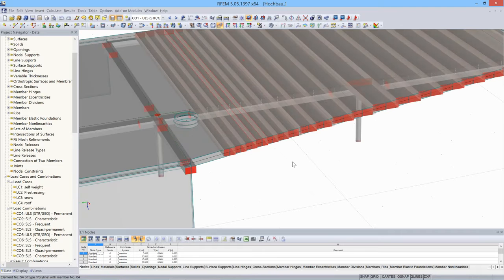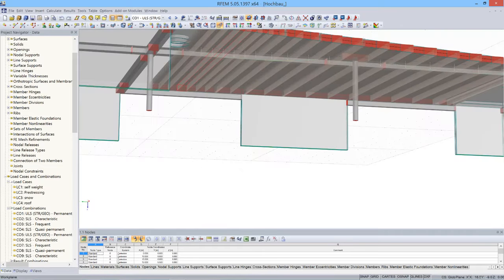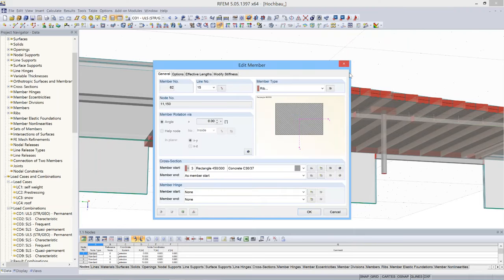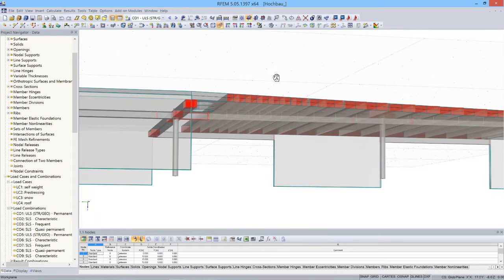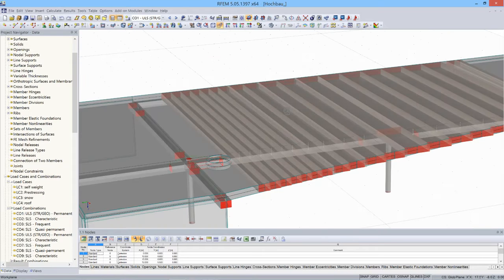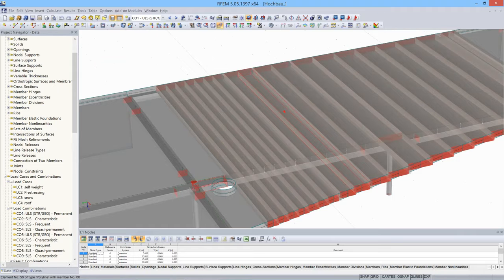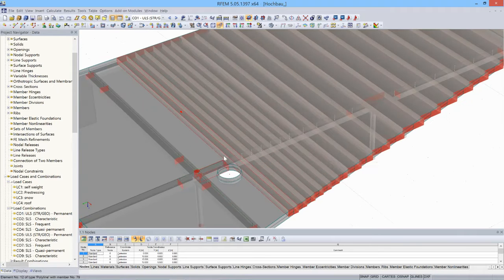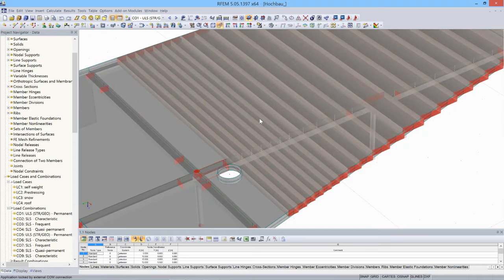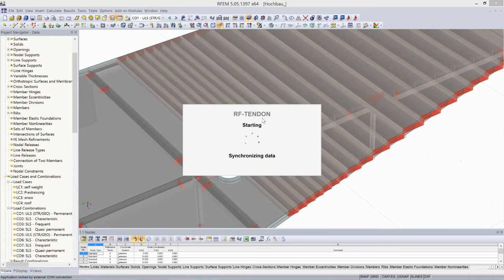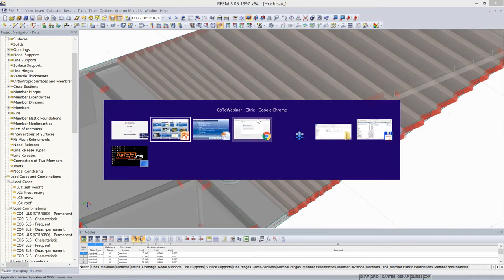You can see here that I have a rib which is linked to the slab, and RFEM can integrate internal forces from a defined width of the slab together with the rib, and we can get the T-section, which is then used in the analysis and in the design.